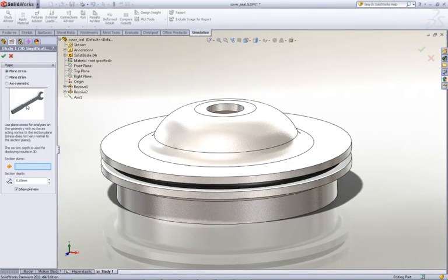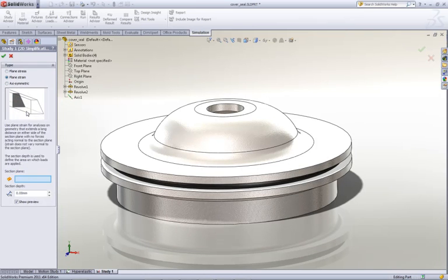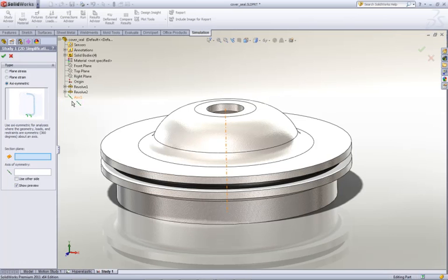For things that are fairly thin but of constant section, we can use plane stress. For things that are like a long extrusion, like a dam wall, if you want to just do a study on that, you can use plane strain. And then we have axisymmetric for something that's a revolved body.